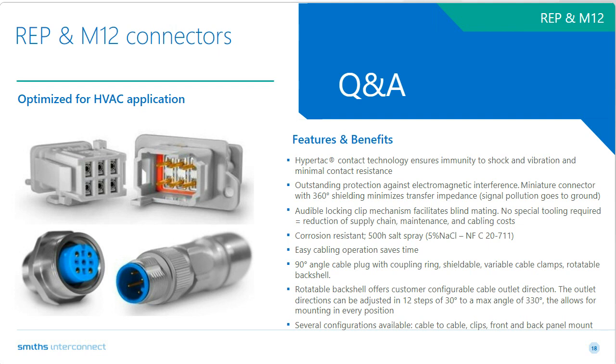If you'll remember, I talked in one of the earlier slides about how, if you put humidity and temperature together, the temperature obviously contributes towards thermal expansion and contraction, resulting in micro movements within the contact surfaces, which creates fretting action. But humidity ultimately deteriorates material properties over time.